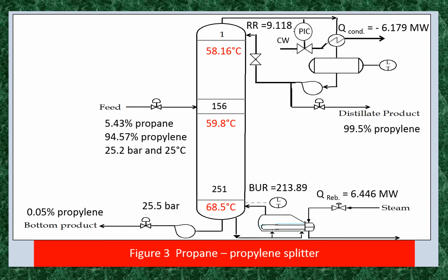Illustrated in this figure is a distillation column operated by an automatic process control system. The column has several key process variables that need to be controlled. For example, feed rate, reflux flow rate, column pressure, reflux drum level, etc. Let us consider one of the key variables, the pressure, for our understanding of process control system.